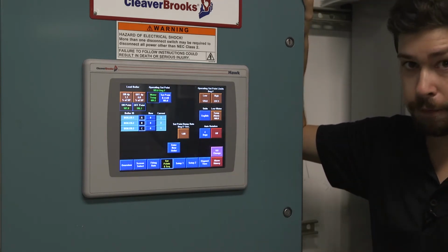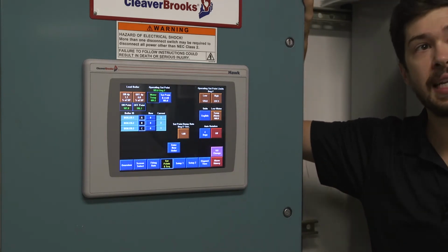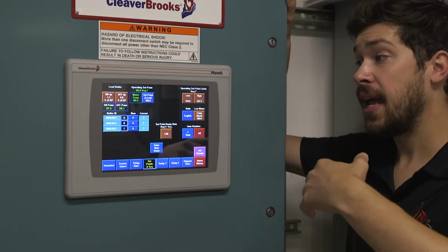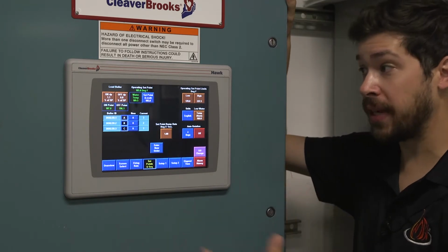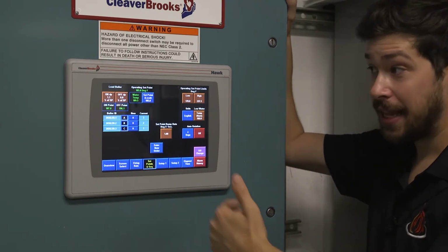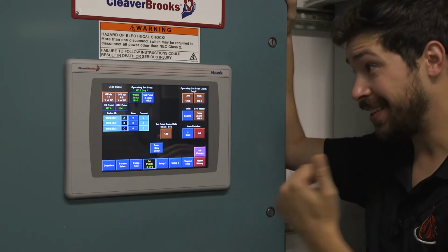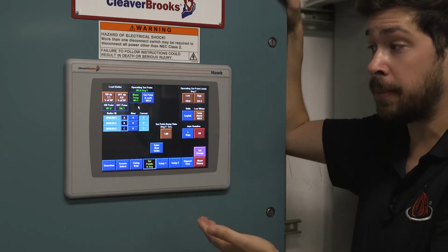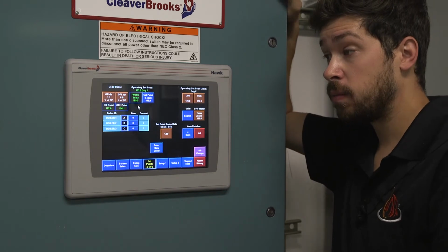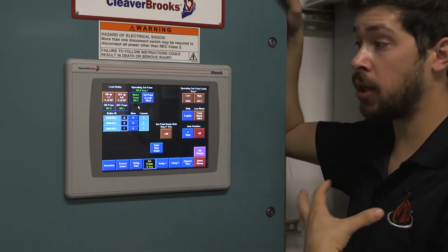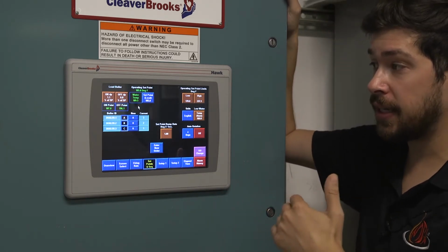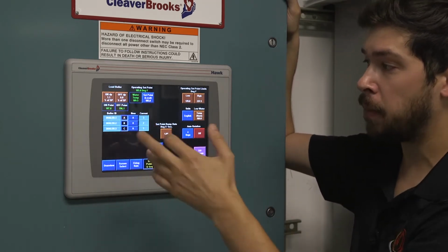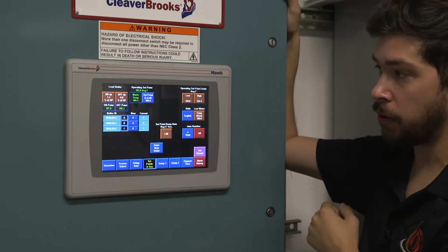It doesn't just flip on like a switch. So we need to give that boiler time to do its thing, and for those next couple of minutes, the temperature is just going to keep dropping and dropping. By the time the boiler turns on, the water temperature could very well be 180. So we want to give it a little bit of a head start. That's the purpose of having your on point above your local set point.